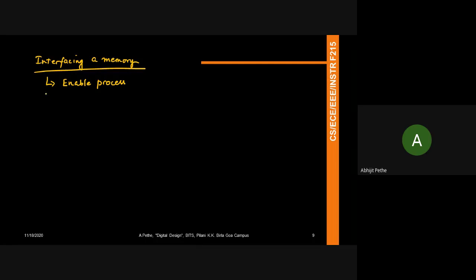to access it. Then, if you look at the data sheet of any memory, it will have things like access time, write time, etc., and this will be a range. There will be a nominal and there will be a worst case. Depending on what kind of designer you are and what kind of risk you want to take in your design, if you want to be a good safe designer, you would normally pick all the worst cases and use that to design your circuit so that there are no issues. But obviously you can trade off speed for some functionality by moving to nominal.